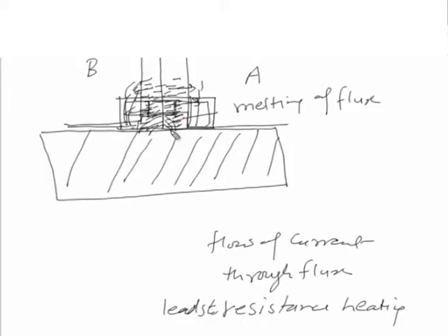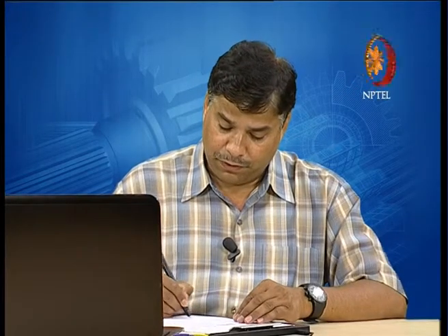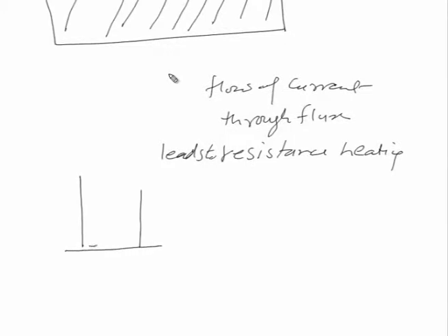To maintain them, these copper shoes on both sides are water cooled continuously, so that they stay within a safe temperature limit. Once a sufficient pool of molten metal has formed, like in this diagram, well covered from both sides by the copper shoes, solidification will start in the bottom side.